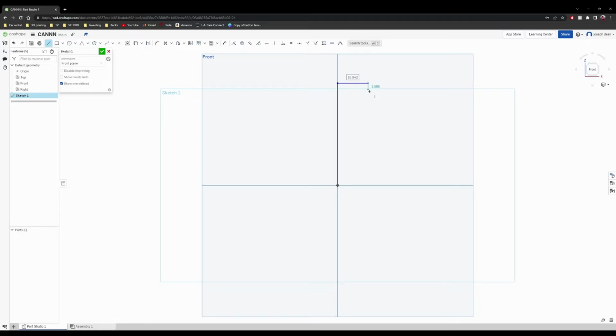So we'll do this for the top. This is the top of the can. And when you're drawing these lines, you can escape by right-clicking. If you have a sketch tool open, it will follow you anywhere unless you click that or hit escape on your keyboard. So I'm going to use this tool right here, the conic. It's good for making curvatures. You dictate how far it goes and then what the curvature is. So I'm going to do it like this.